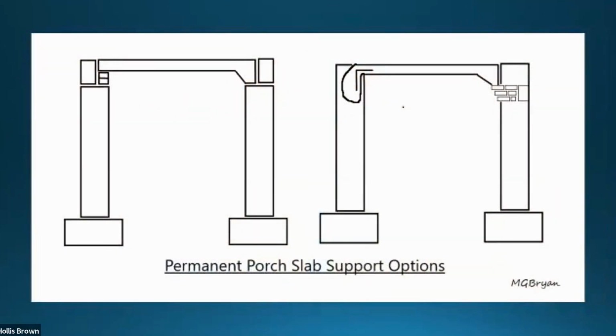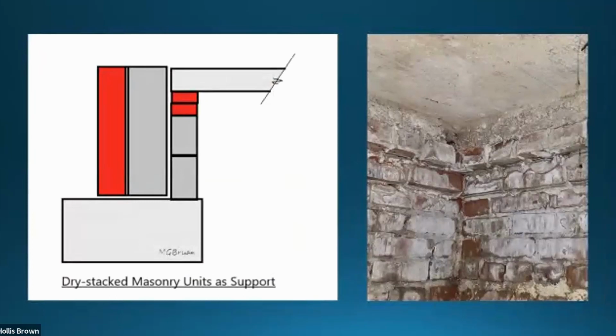You either have to go ahead and pour the concrete originally into your stoop, either in through open cores, or just build it a little larger so that it has a ledge for it to pour onto. It really costs nothing to do this, but builders never listen to me. They always insist upon the fact that it doesn't happen. In fact, after the fact, when I pointed it out to them, I've told them, just stack some concrete block up on the footing to catch it. That'll do it. You don't even have to mortar them in, but they don't do it.